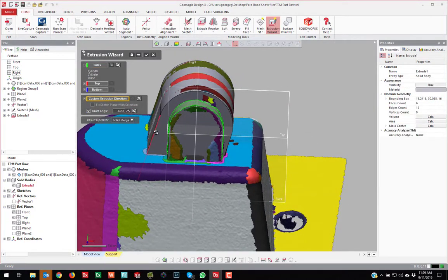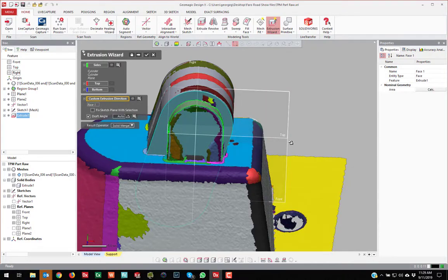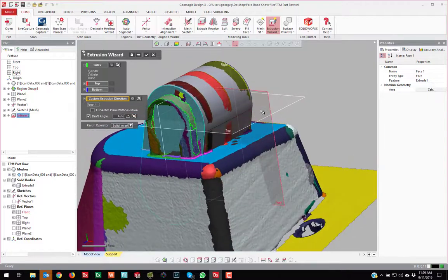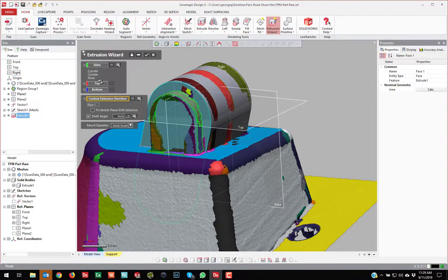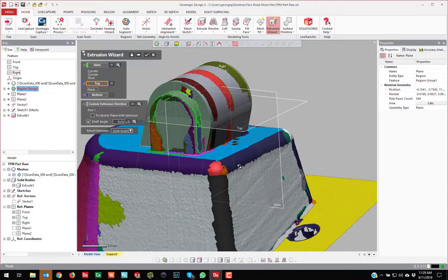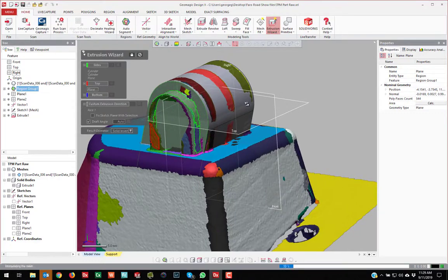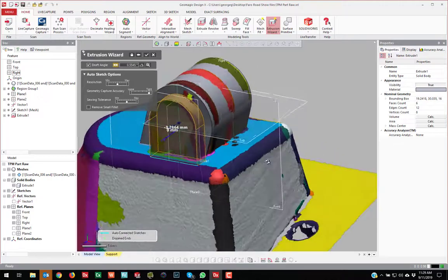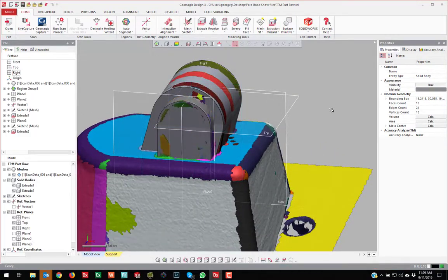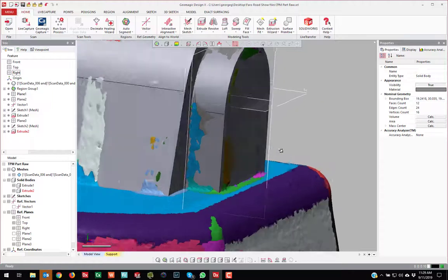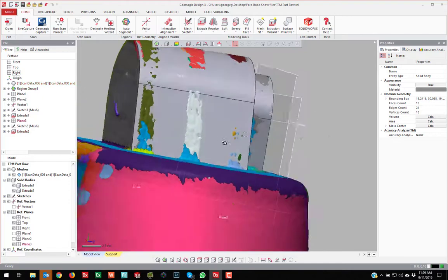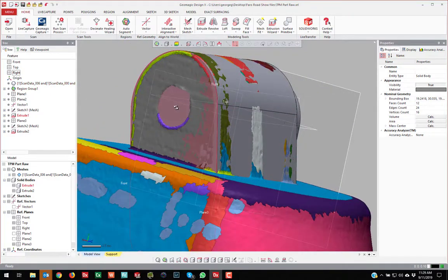And then I can tell the software that it needs to put the sketch on that CAD face there. And then we'll just tell it to insert another solid there, and that it needs to extrude up to that plane. And then hit next. It automatically draws and extrudes that for me. And then when I hit OK, you see that it created that on the side there. Now, it didn't create that internal cutout.